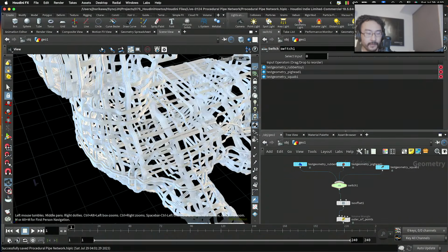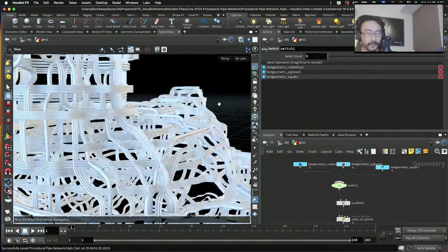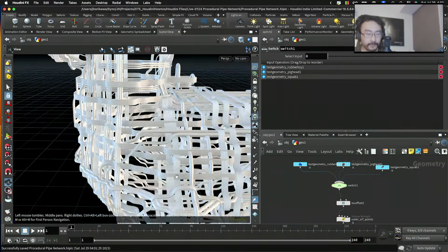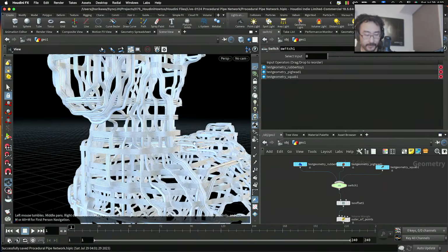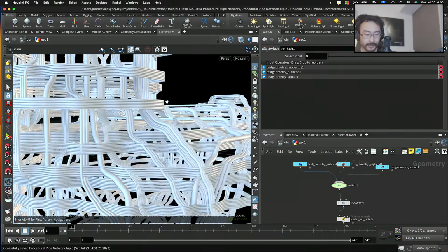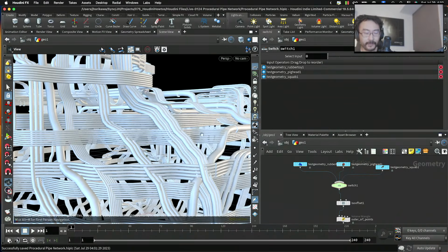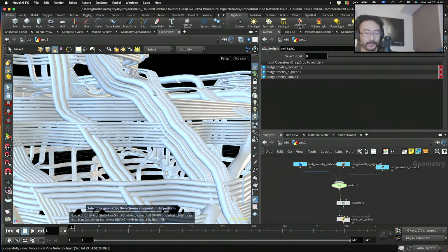If I use 80 for the rubber toy, seems like the resolution is a bit too high. So in those cases I need to probably reduce the smoothness and increase the value for the resample to make this cornered.